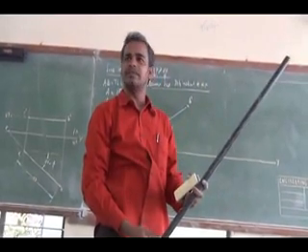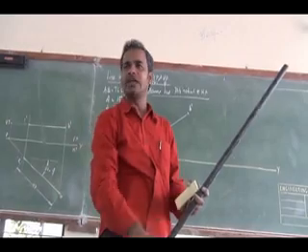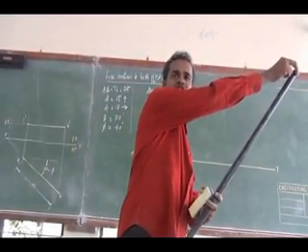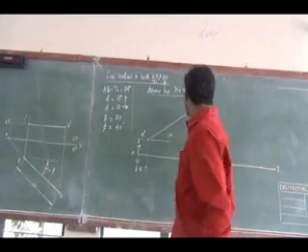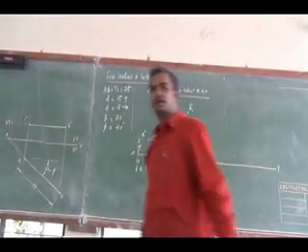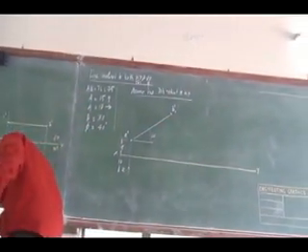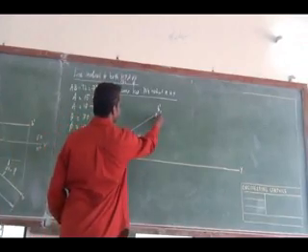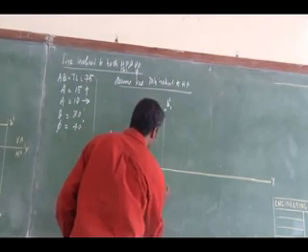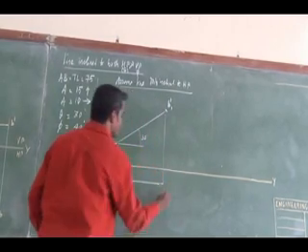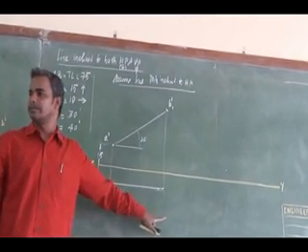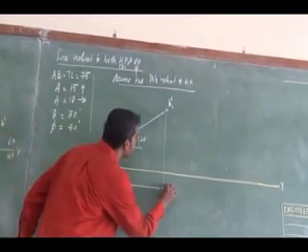So I am assuming it is parallel and only inclined, so I will have an assumed location of this end. This end's projection I can notate as B1 dash. Right, it is an assumed case, so that is B1 dash. Now I can project this. So what will the top view notation be? B1. Right.